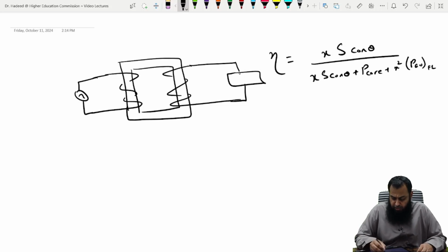Because this load is a fixed load for a factory setup where a process has to happen throughout the day, probably for almost all the year, this transformer can be adjusted during the design stage such that we can optimize this denominator for attaining the maximum efficiency.